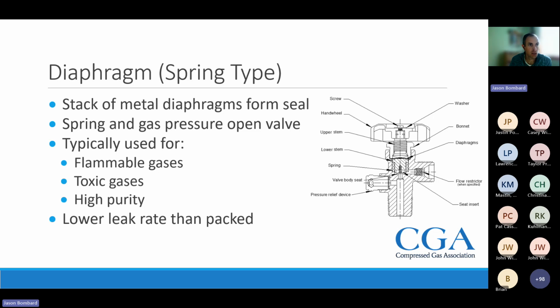For cylinders, the isolation valve would typically be the cylinder valve, and then the relief valve, there's a few different varieties based on the gas service. So most of your higher pressure gases will have some combination of a rupture disc with or without fusible backing on it. In LP service, typically it would be what we call a CG7, a spring operated, reclosing valve. Acetylene uses a fuse plug, which is just a fusible metal without a backing. There's no rupture disc on those.